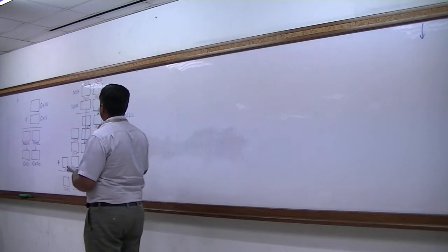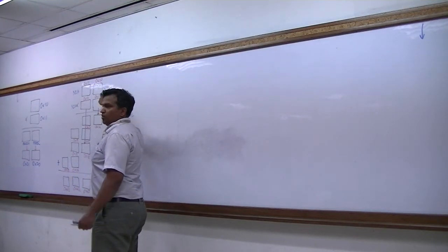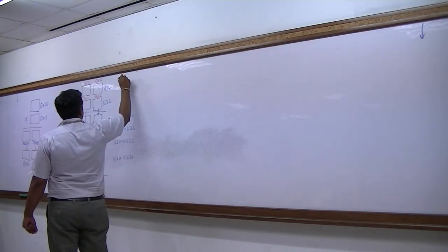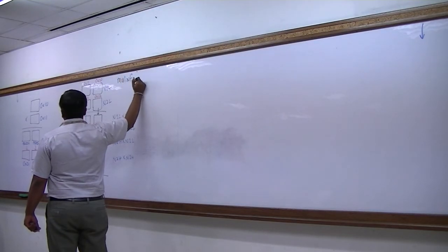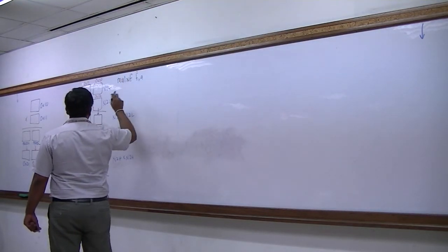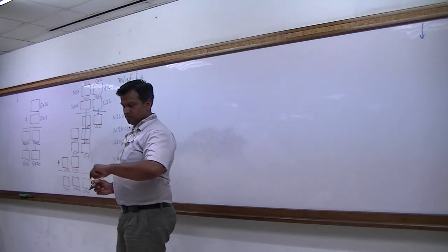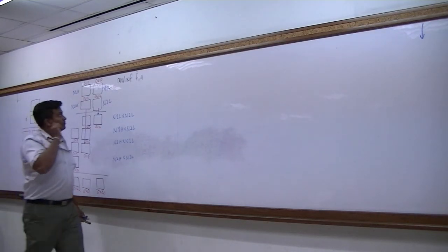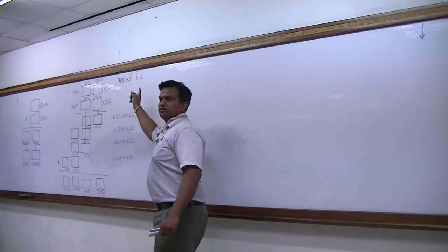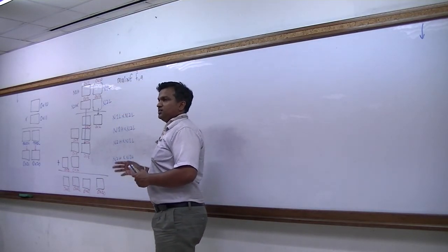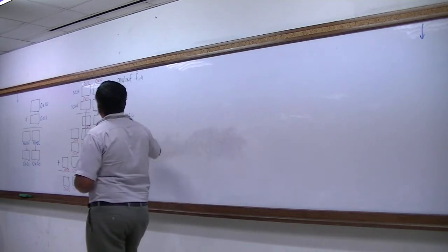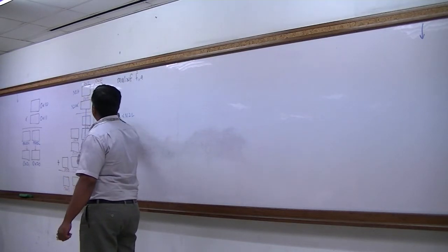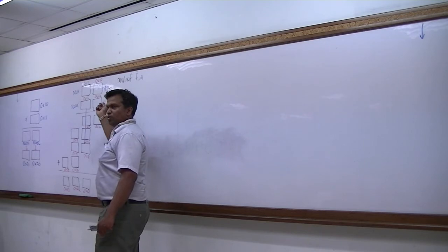So let's try to do the first one. In order for you to do this one, we have to use this instruction. We have used multiply working register, file register. You all get it, right? The other instruction multiplies a literal with the working register, so we're not doing that. We're going to do this. That means one of it you need to move to the working register. So now we want to solve this first one. Any one of it you can move to the working register.